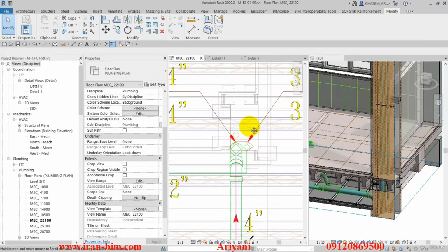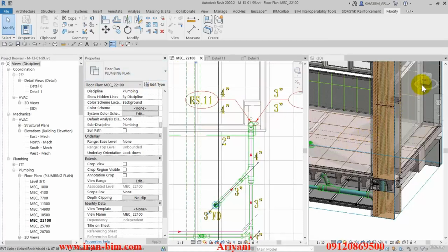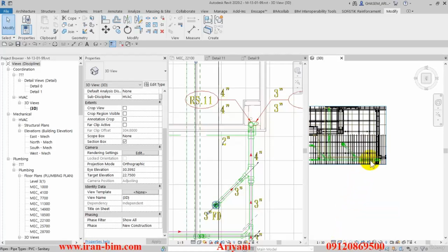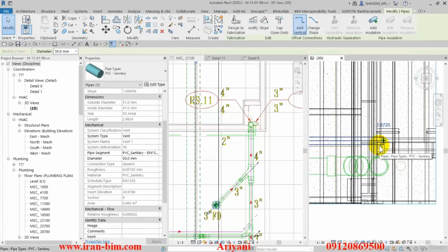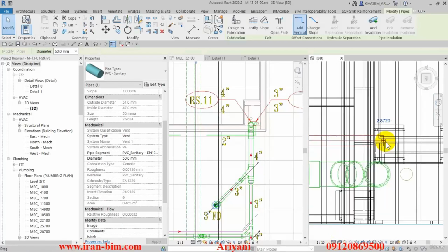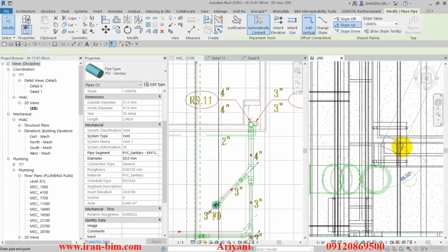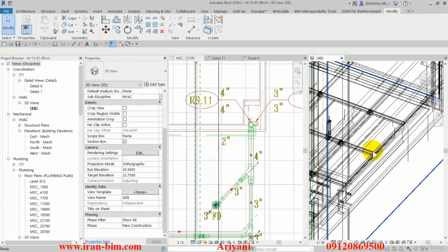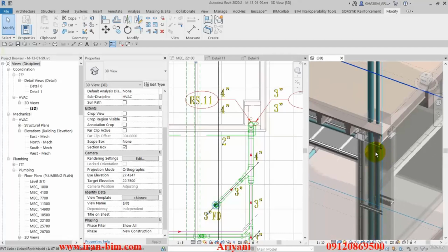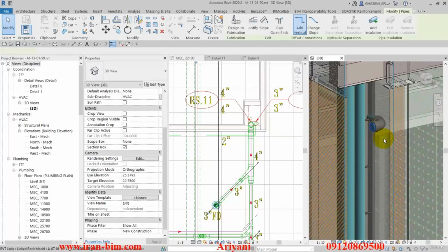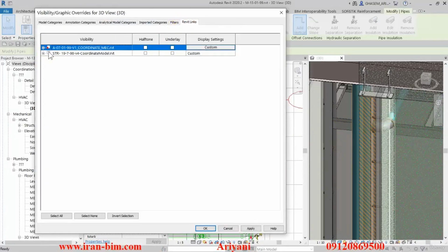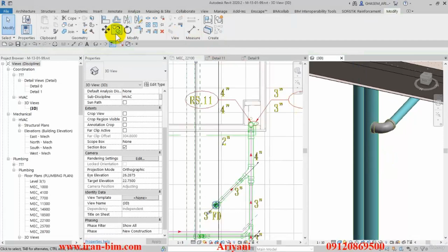And alright, now let's go over to the 3D view, and over here I'll put this on wireframe settings, and then we move over here. Right click here and select the draw pipe option. Then we draw the pipe towards the right direction and then down to draw this piece. Now let's change the angle of the 3D view and go over here to see what's what. Open up the visibility graphics menu once again, and under the Revit links tab, I'll uncheck the visibility of the architecture for now and hit apply.